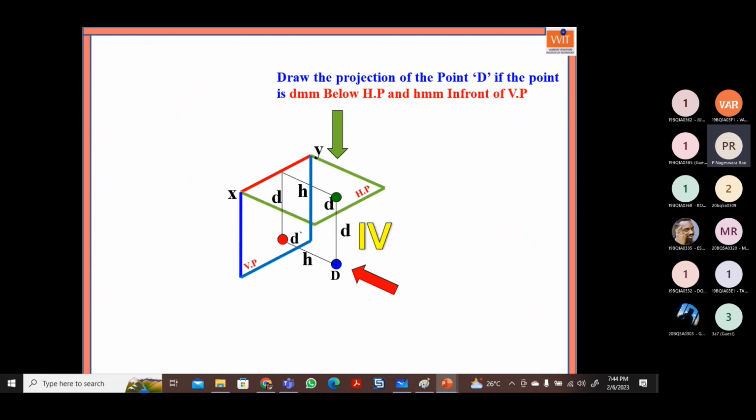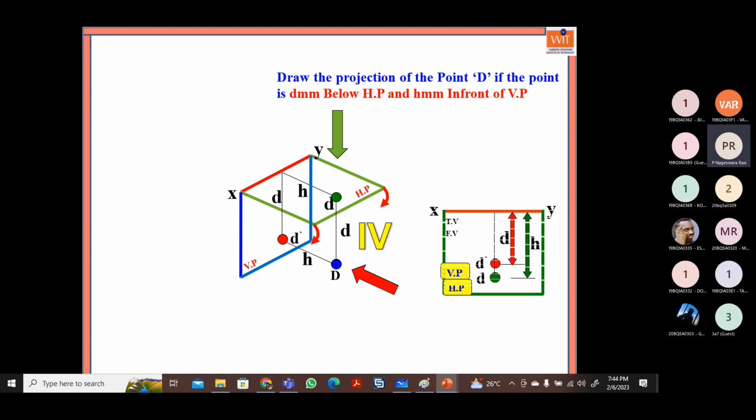See, next the fourth quadrant. When the horizontal plane is rotated towards 90 degrees, it goes towards the downside, so it becomes like this. Again, for an object in the fourth quadrant, or fourth angle projection, both the front view image as well as the top image have to be drawn below the XY line, opposite to the second angle projection or second quadrant. So we are not preferring the first angle projection, sorry, we are not preferring the second angle projection.